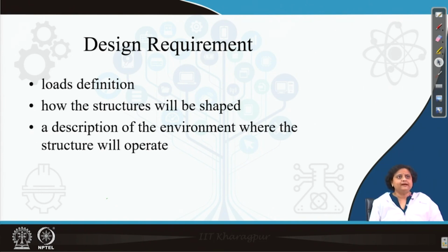Similarly, if we are using the aircraft, say if it is a navy aircraft, if we use it mostly in oceans, in seas, then the aircraft will have to withstand a lot of moisture or humid environment, and therefore, we have to select the material of the aircraft structure in such a way that this moisture can be resisted.